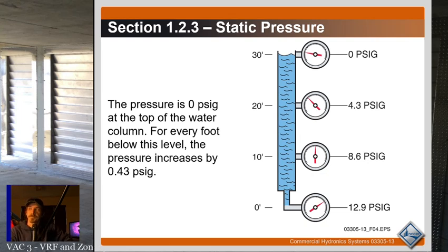Well, that should be kind of obvious, right? Here's the thing. We only need to circulate water in the system, so we need to make sure we have some amount of pressure throughout a boiler system. We don't need a lot. We just need enough to make sure that it's full of water and there's no air in it. So we have to have enough pressure at the bottom of the system so that at the top, we've got at least some pressure left, 1 or 2 psi.